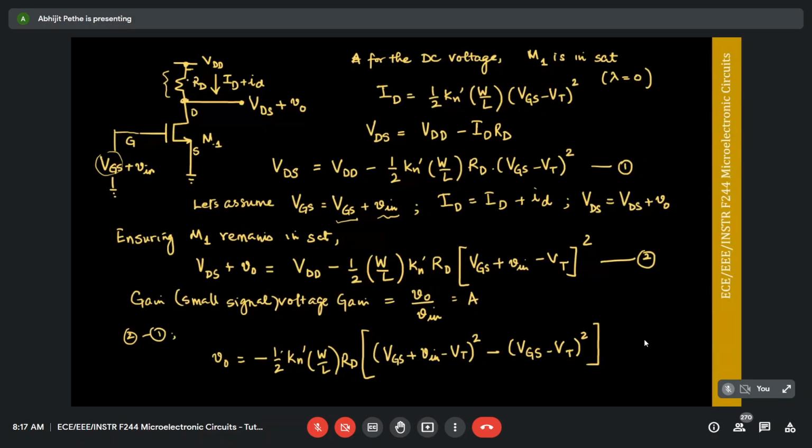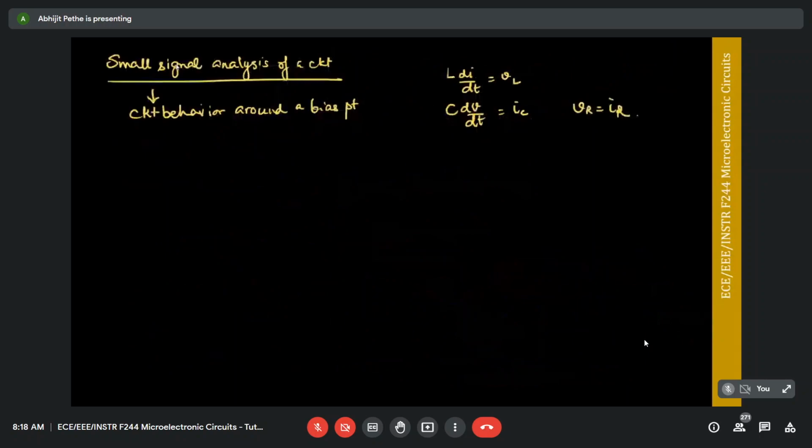No, right? So remember, the voltage at the supply does not change. There is no AC signal there. Similarly, what can you say about the voltage at the ground? It's also constant, it's zero. So these two voltages are not changing because of the AC analysis. What changes is the current flowing. So this node, if you look at the AC analysis, the voltage does not change, the current changes because of AC. So this looks like an AC ground. Okay? That's an important concept that we'll use when we do small signal analysis.